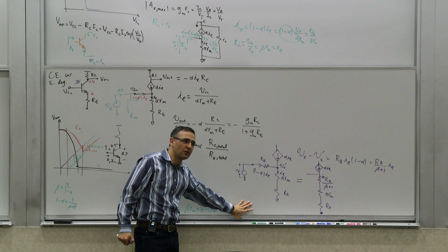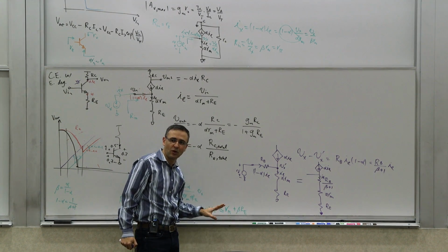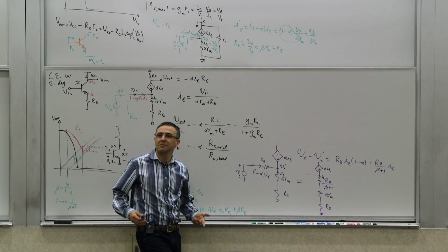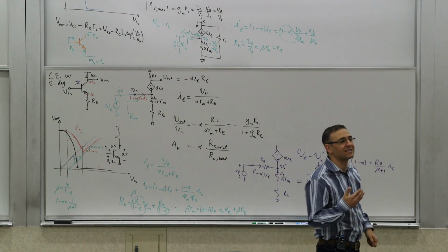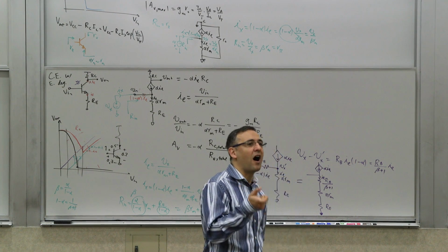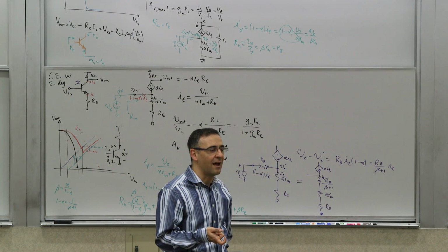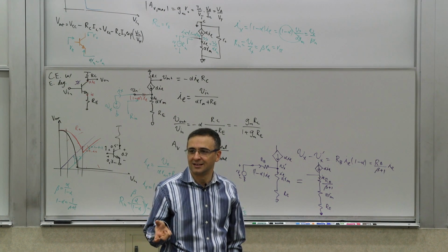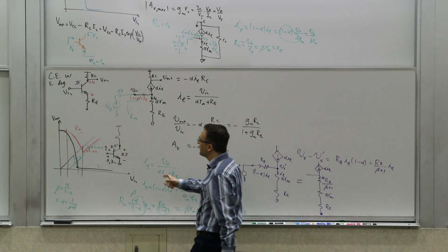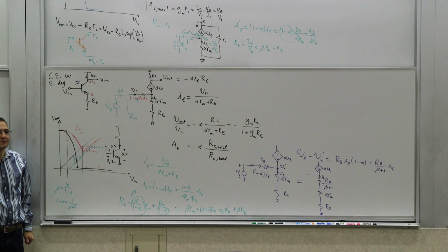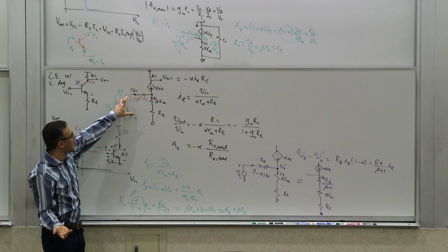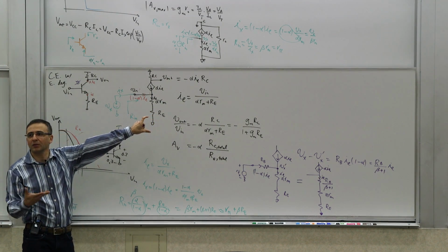If you set Re to 0, you will see that it reduces to that resistance. It reduces to R pi. And whatever you put in the emitter gets multiplied by beta. So it makes it a good kind of what? Sensor for what? Is it a good current sensor or voltage sensor that has a high impedance? A voltmeter, a good voltmeter or a good ammeter? A voltmeter. It's a good voltmeter. So it becomes better for measuring voltages because it loads it less, which means that it allows you to maintain the voltage unperturbed depending on what the source resistance is.